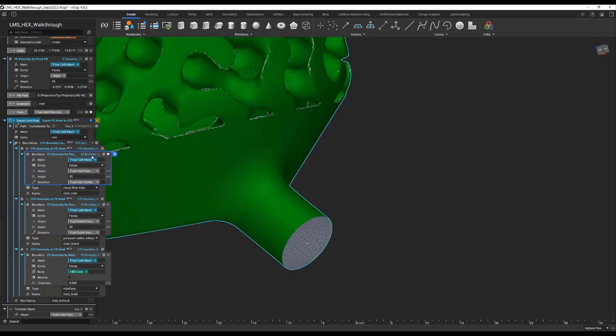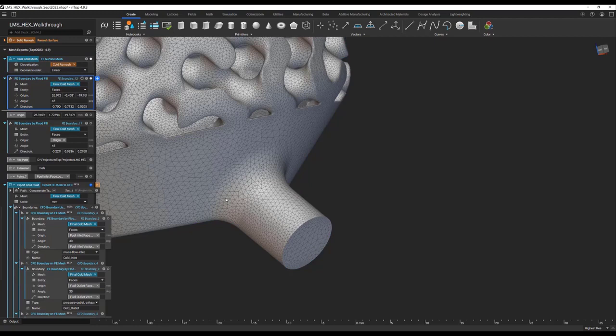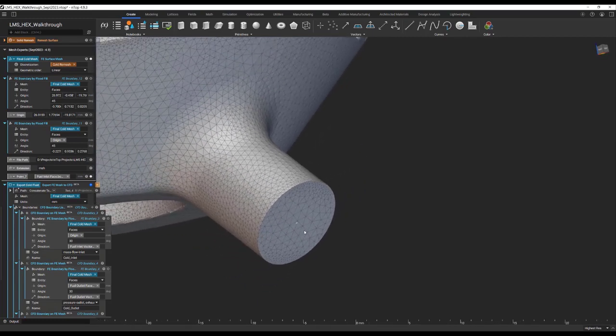So this is the mesh, the FE boundary by flood fill, as we had it set up. What I did was do another filter mesh by flood fill. I took that original origin point that came from it, so that's this block here. And if I insert that into this block, we capture the inlet face. If we look at where that fuel inlet face point is, it sits just barely within the domain, it looks like. So that could be a bug.